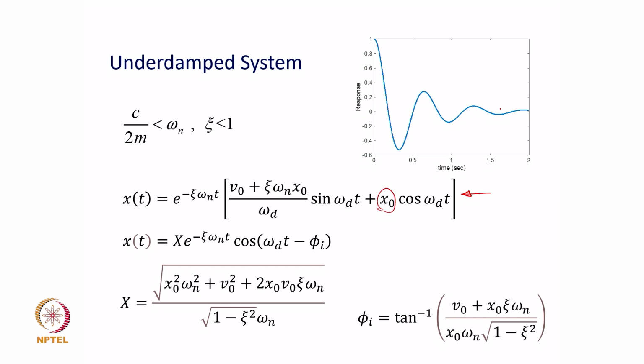Okay. So, that is basically your underdamped vibratory system response. Given your vibratory system, which you will convert from a physical vibratory system by making a simplified model something like this, which has its own k, c and mass values, if this system is perturbed at t equal to 0, the ensuing vibration response can be obtained by the expressions which are given here.